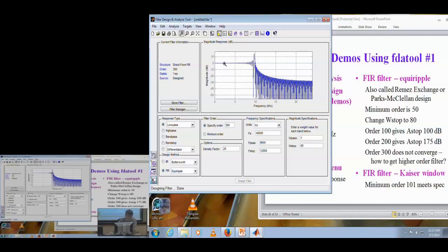Sure, you could look at this as a narrow bandpass filter that amplifies frequencies around 9.7 kilohertz, has mild attenuation at low frequencies, about 15 dB down, and a little better, but still not so big. Maybe from peak here, it goes from 15 dB to minus 15, so about 30 dB of stop band attenuation at higher frequencies. Okay, I mean, who knows? It may have some use out there. But this is not what we wanted. This is not the kind of filter we were seeking to design.